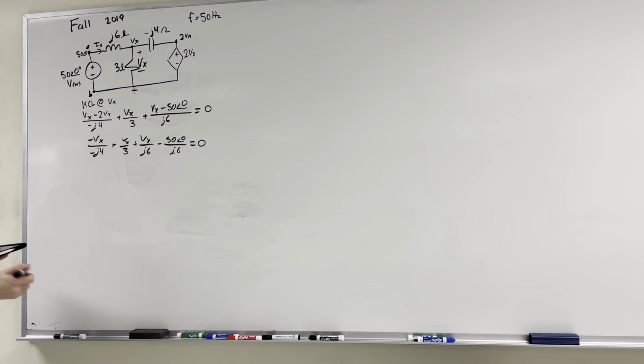So this is going to be equal to 50, phase angle 0, times 6.51. The phase angle of the complex conjugate of this is just going to be 75.5 degrees. And now finally, our complex power of the voltage source, I keep mixing those up, is 325 with a phase angle of 75.5 degrees. Boom, done that part.